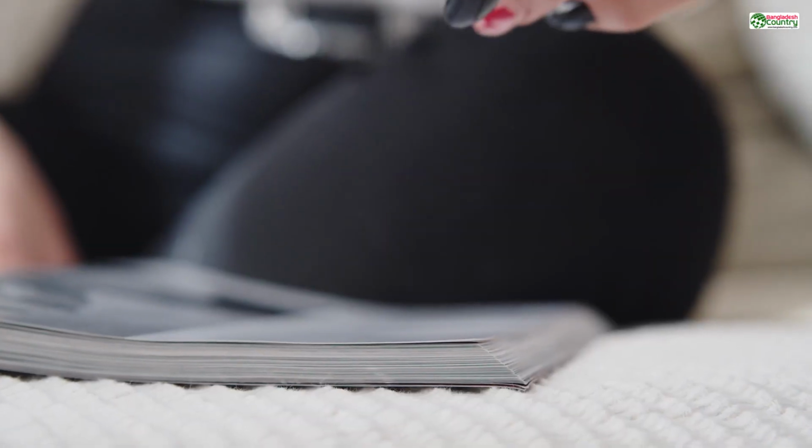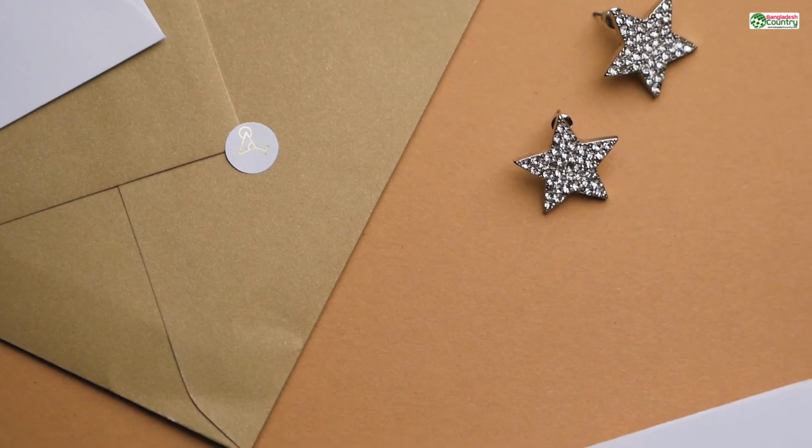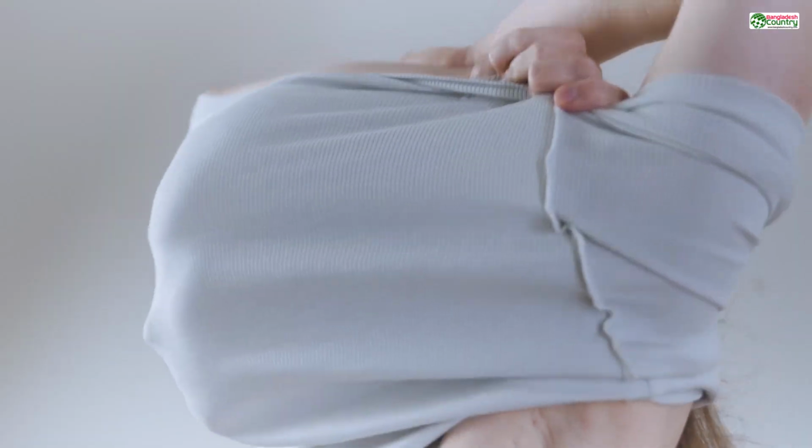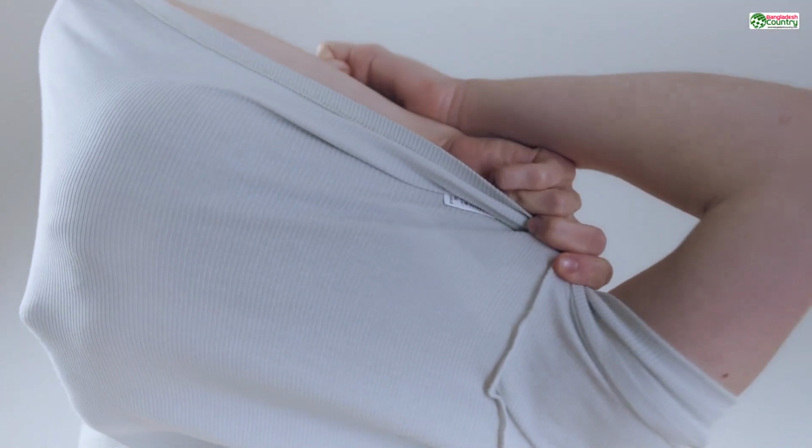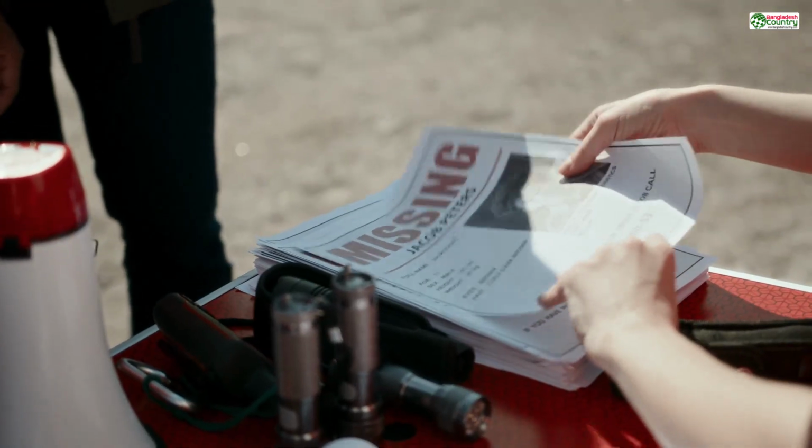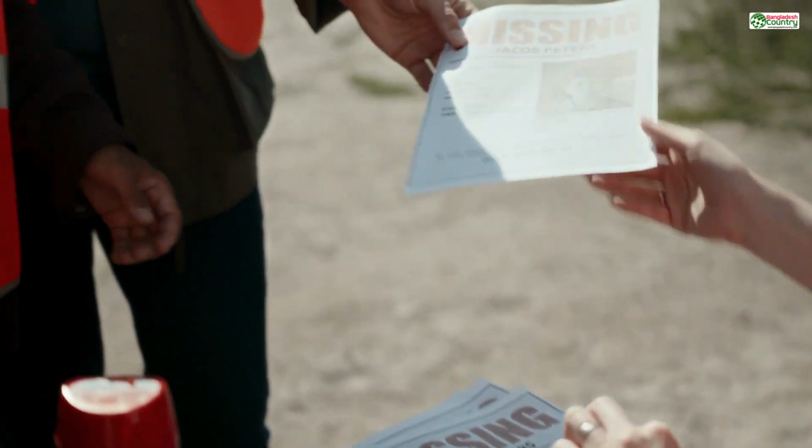It will list, clear as day, the minimum wall thickness, and it's often a number like 0.7 millimeters or 1 millimeter. This is the absolute thinnest your model's walls can be. Your mission is to find any part of your model that violates this rule. Ignoring this number is the fast track to disappointment.